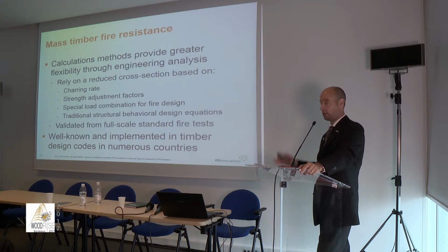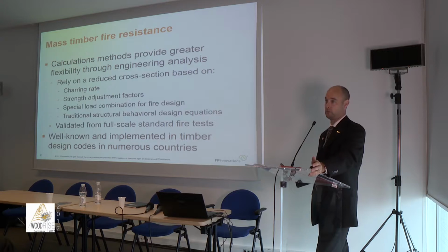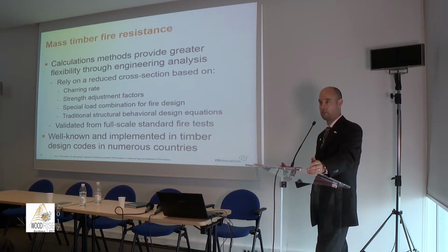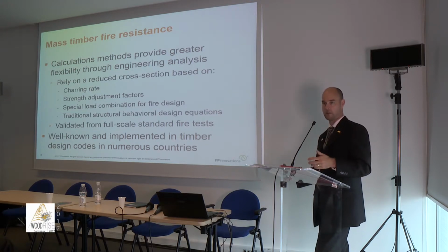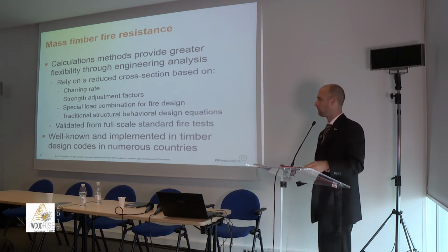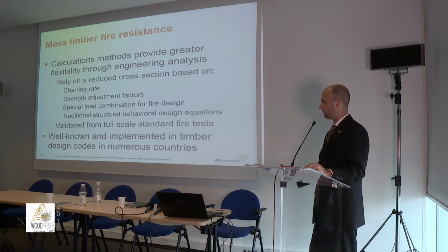Hopefully, luckily, I would say we have calculation methods. Pretty much all countries now have analytical methods to calculate fire resistance. There are many similarities in terms of concept: the reduced cross-section method, strength adjustment factors, charring rates as well, depending on the product. So they're pretty much all the same and all validated methods.